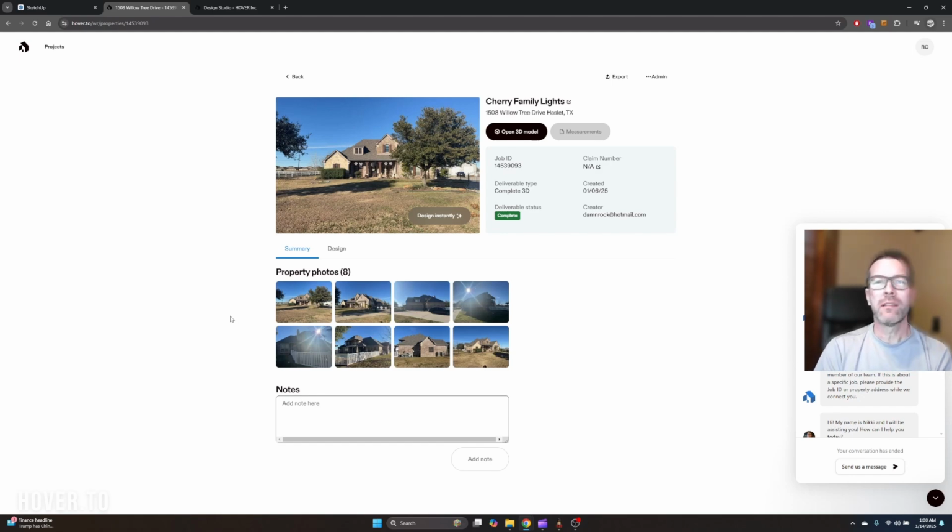If you just want to have a 3D render of your house and you don't want to add anything to it, like let's say in your example, you don't care about trees or anything in the yard. You just want the 3D render of your house, and you don't care that the textures are there, like the brick and the shingle. You're okay with it just being a gray kind of version of the 3D render of your house. Then ask them for the OBJ file. They'll send that to you, and you can skip all the SketchUp steps.